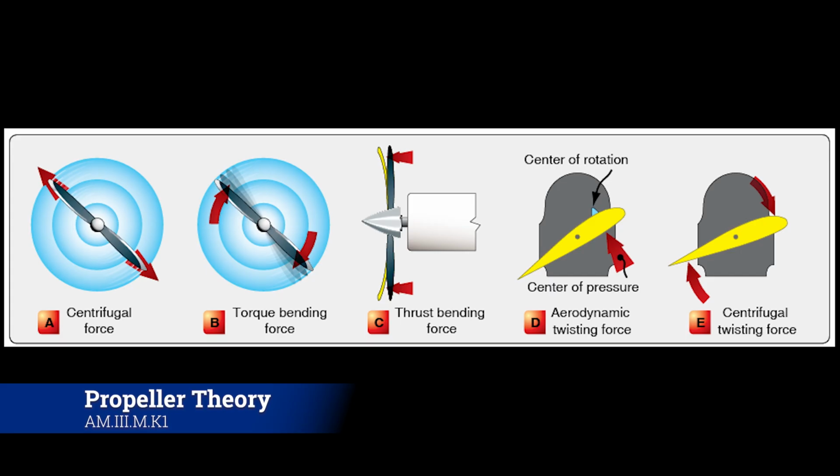Now, basically, as the propeller goes around, one of the things that's going to end up happening is it's going to want to cone. It's going to want to lift off. You can totally see this with helicopter blades. As a helicopter goes to lift off, you'll always know the pilot's pulling collective, because you'll be able to watch the blades. They'll go from a flat pitch to more aggressive, and as it gets more aggressive, the blades start to curve up on the end. That's called coning. As the blades cone, eventually it gets to a point where the strength of the blade and the strength of the hub overcome that coning effect, and the blades just start to produce lift and lift the helicopter off the ground.